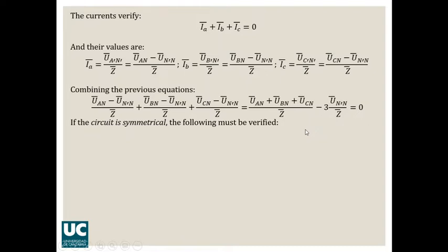So then we should have this fraction equal to this fraction with a positive sign. As you can understand, this fraction is 0. Why is that? Because here we have the different values of the line voltages, and as you know, we started by saying that the system is symmetrical. That means that the three absolute values of these phasors are equal and they are shifted by an angle of 120 degrees. That's why the sum of these three phasors is 0.